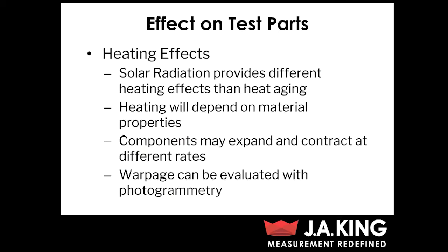So solar radiation is going to provide a different type of heating than heat aging, similar to the infrared radiation testing that we talked about, it's going to have directional heating. So you're going to have different parts that are going to heat up at a different rate and to a different temperature than other components of your part.